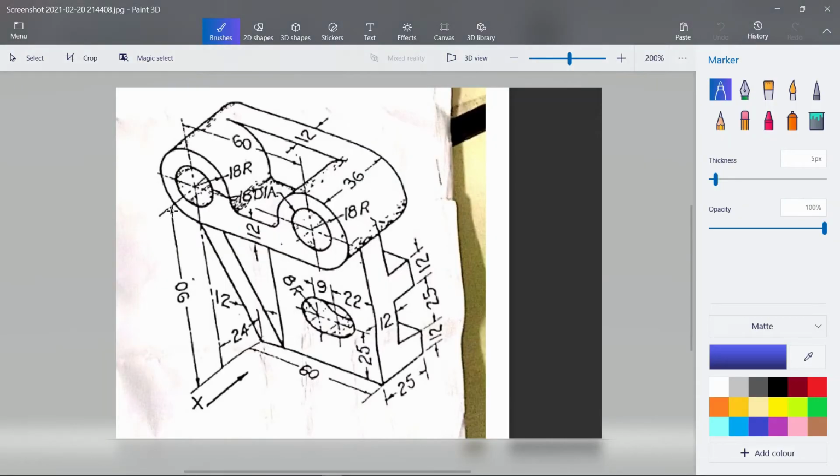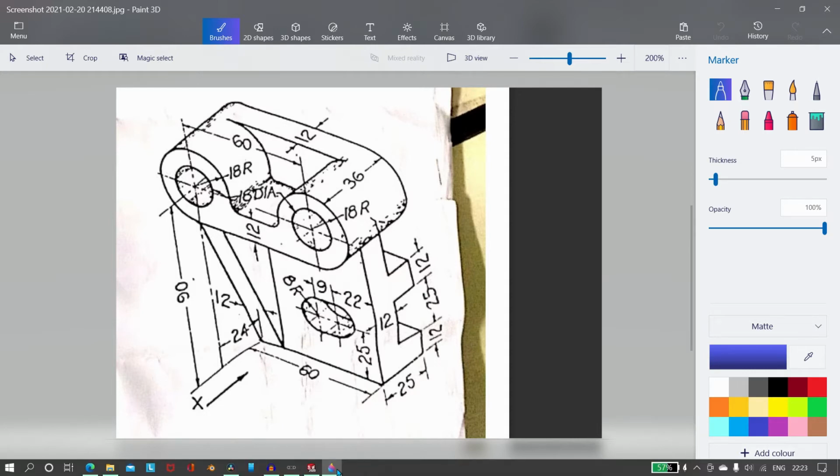Let's design the B shape right now. So I will select, let's select the front plane, or rather than selecting the front plane, I will select the extreme end plane over here. So I'll select that plane, and then we will draw two circles. As you can see, these circles, their center lines pass through the edges of this inverted F. So I'll just show it how it works.